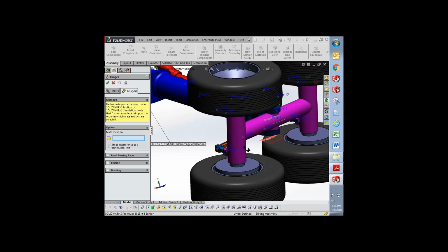But if you have two planes, the point could be arbitrary. Or if you have two axes, it could be anywhere along the axes, which means the motion is here and that point is there. You've created a big moment between what's moving here and the actual mate point. So you use points to dictate where motion has to calculate the forces. So that's where I also use it.